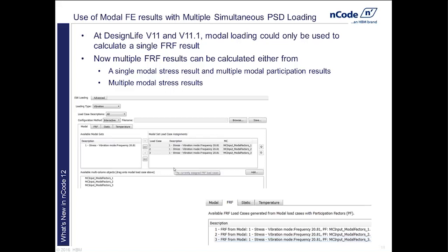So this finishes the changes we made to the vibration solver in terms of multiple simultaneous PSDs. It now enables the complete use of modal results, multiple PSD locations, application of various static loads, and also the application of the temperature load cases as well.